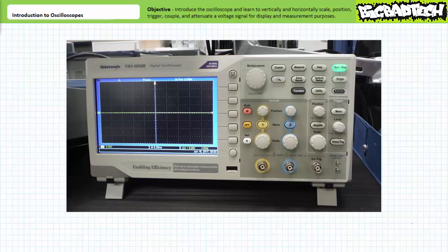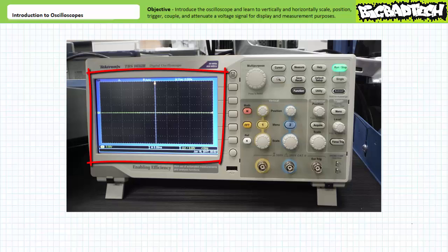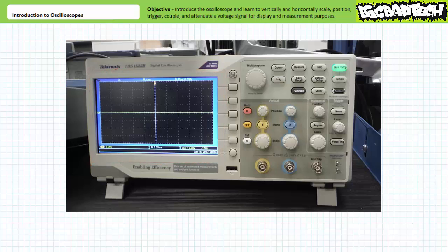Bottom line up front, an oscope is exactly like a voltmeter, only it displays a picture of voltage. An oscope takes repetitive samples of voltage, then draws the result on a display that one can zoom in or out on, shift up or down, left or right, and with pretty minimum effort perform some basic measurement, comparison, or mathematical operations on. The oscope is a powerful, sophisticated tool. However, the scope of today's activities is to limit ourselves to only the most basic, essential, and effective functions of the oscope and leave the rest for later.